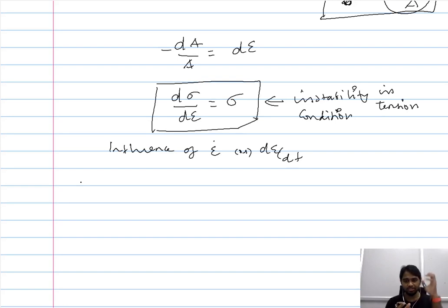However, when your test is based on the stress, then you have to be careful about the cross-sectional area, and once you observe the decrease in the cross-sectional area, you have to be very careful about the amount of load that you impose so that it is proportional to the cross-sectional area. So in order to avoid that, generally people devise the tensile test with strain as its controlling parameter. They give different amounts of strain, they keep on increasing the strain, and they calculate how much stress is required, and they plot the stress strain curve.